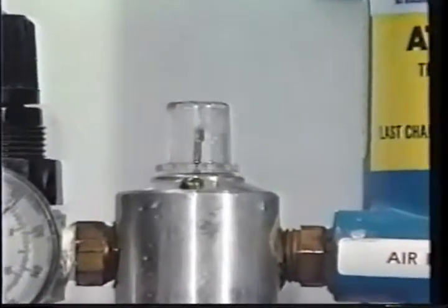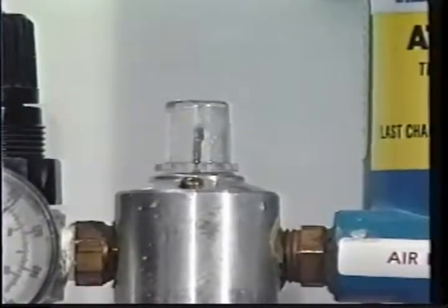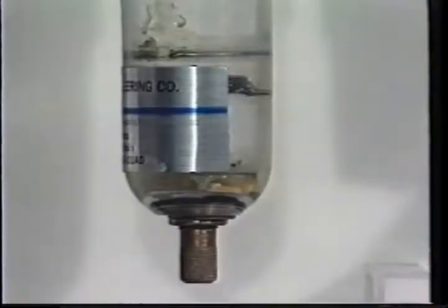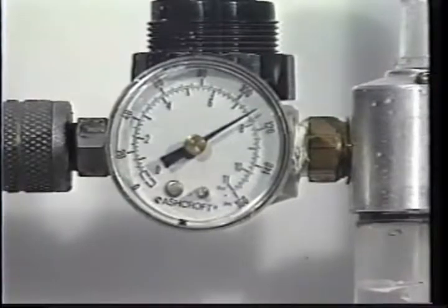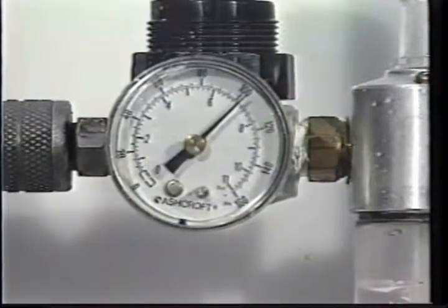Moisture is introduced into the air by a lubricator at a rate of 1 drop per second. The condensed water flows into the separation section and drops into a piston-activated drain, specifically designed for this small unit. Pressure swings caused by interrupted airflow from an intermittent operating solenoid activate the piston drain to discharge condensed liquid.